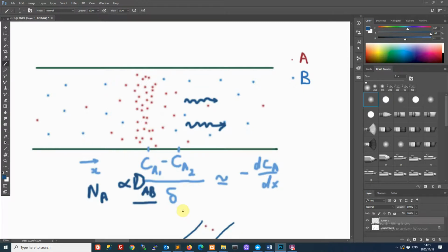Well, all that work has been done for us. There has been a great deal of research into this and a great deal of work done on estimating the diffusivity. And in fact, it's not complete, because we are still developing new correlations for new situations. So quite often what we do is classify the types of molecules involved. For example, highly polar molecules will have one expression, and non-polar will have a different expression.